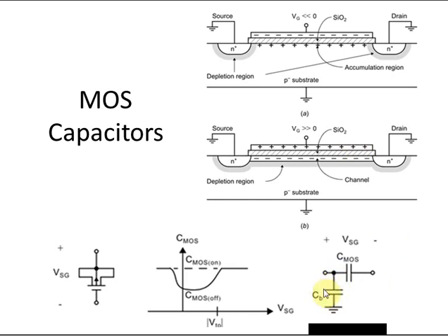And finally, there's something not shown here in this model, but recognize that one side of this parasitic capacitance, CB, is connected to the P substrate, and the P substrate is generally quite lightly doped and therefore has quite a high resistance. That can lead to loss and basically heating in the substrate and therefore energy loss in your circuit. So that can also be a problem.